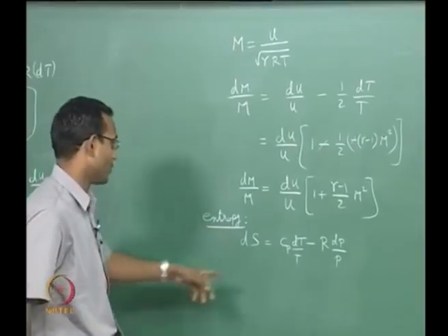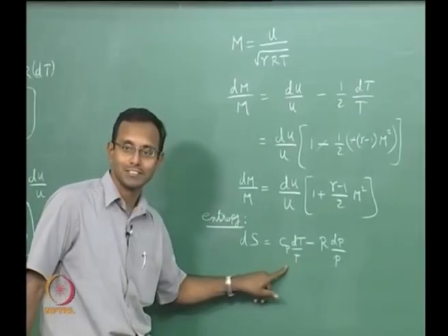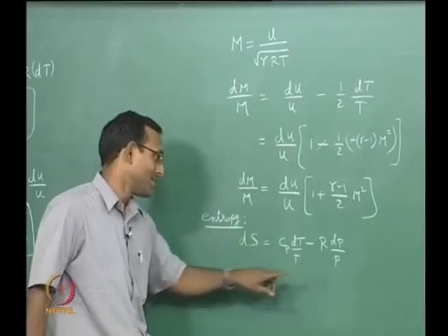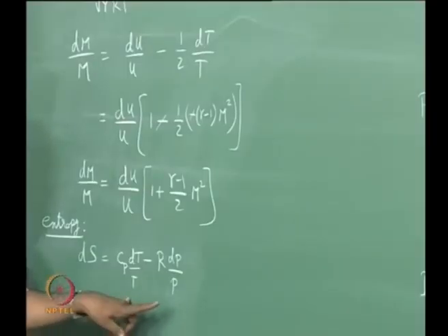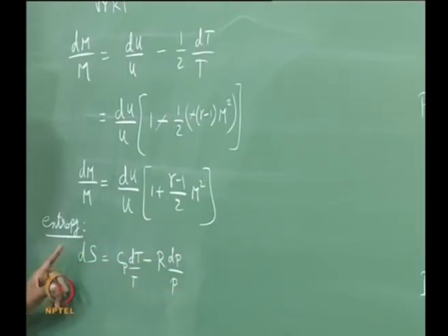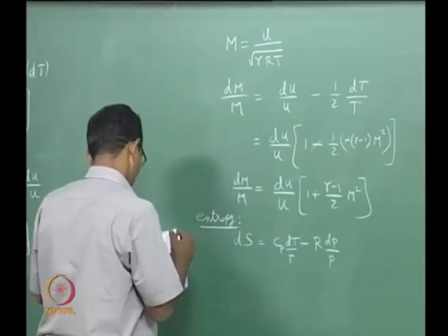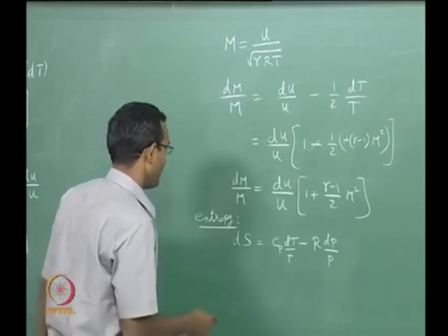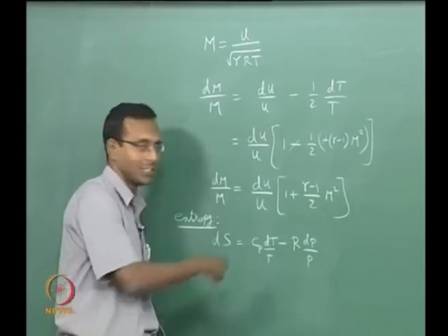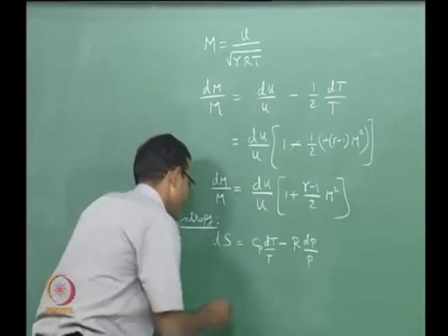Okay. This is how you get the isentropic relations. Remember long time back we did the pressure to temperature isentropic relation. We got to this form, and when you integrate and put delta s equal to 0, you get to that particular relation between P and T. Yeah, that is sitting here. So I will start from this particular relation. Now what should I do? I want to get everything in terms of du by u. Start substituting everything else inside here.